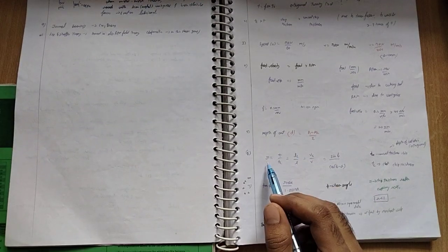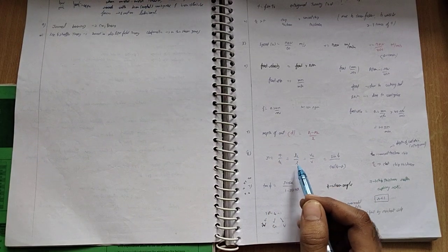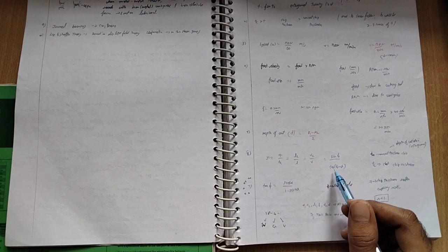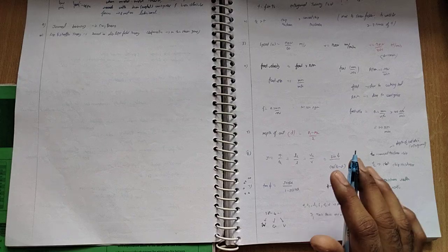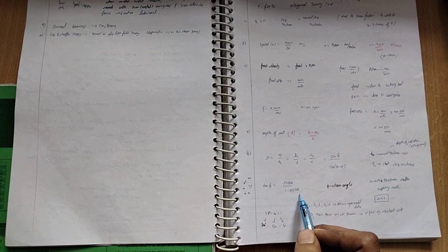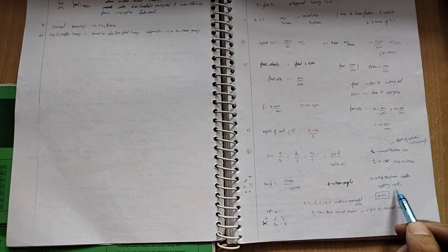Next you can see r, the cutting ratio, equal to t divided by tc, lc by l, and vc by v, and that equals sine of shear angle divided by cos of shear angle minus alpha. Mainly, tan phi equals r cos alpha divided by 1 minus r sine alpha. This one is the shear angle. r is the chip thickness ratio, the cutting ratio, and r is less than 1. I think you can understand.